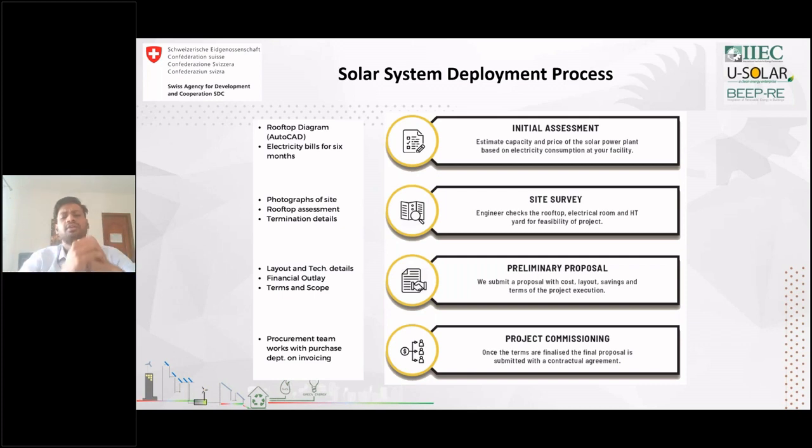One more major factor with shadow effect on a solar PV module is that if you have installed a few of the modules in shadow regions and they are repeatedly affected, then the module will start degrading also, and you'll not only lose the generation for that particular time where the shadow has been cast on your modules, but also have a long-term effect on your modules.